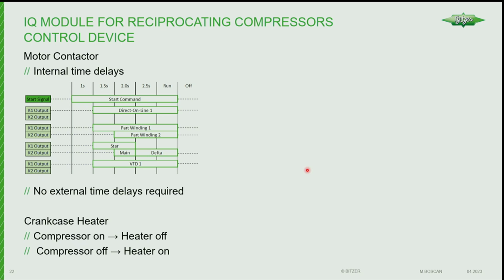Typically head fans are on low temp all year round, right? Low temp's on even in the middle of winter because they're just on with the compressor off. With the CMRC for HFCs, we read the discharge temperature and only turn the head fan on when the discharge temperature exceeds 245 degrees. So it saves a little bit of energy, but if you have a ton of stores and a ton of low temp and head fans on all that, it adds up, maybe at a corporate level. So there's no reason to run a head fan in the middle of winter, other than the logic is not set up to turn them off. It's just easier to run them that way.